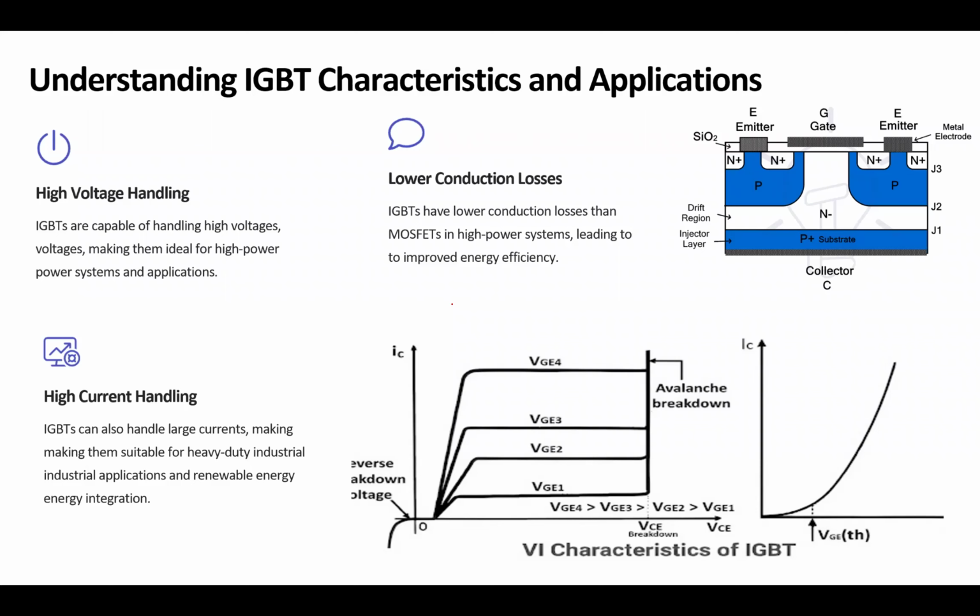When we talk about the output characteristics of the switch, which is the current that is allowed to flow versus the voltage over the switch between the emitter and collector, this is the on part. When we get on and the current starts, after a certain amount, like the MOSFET, the current gets saturated, so it won't allow any more current.